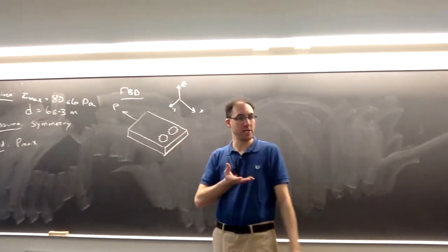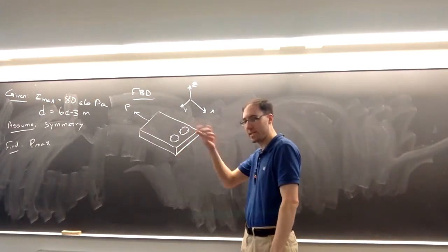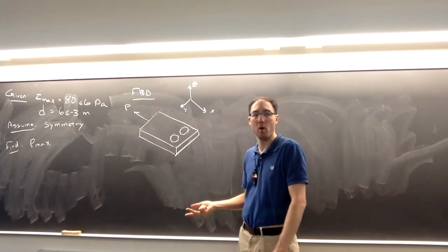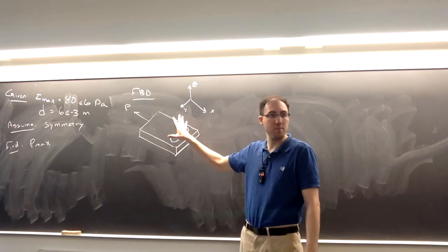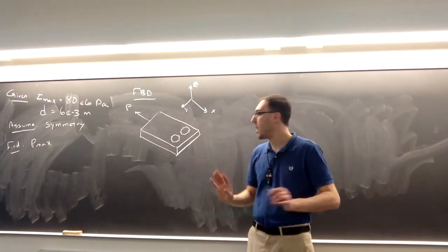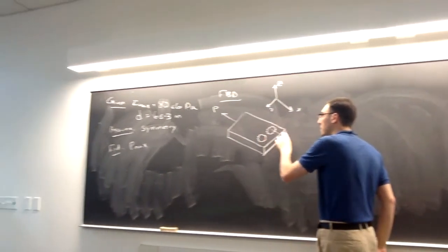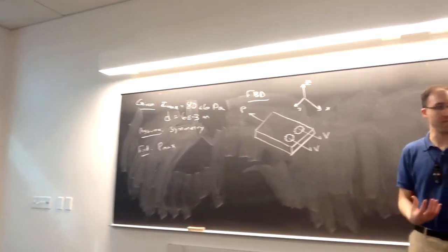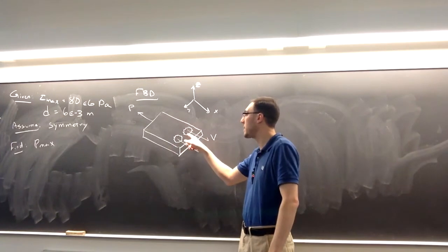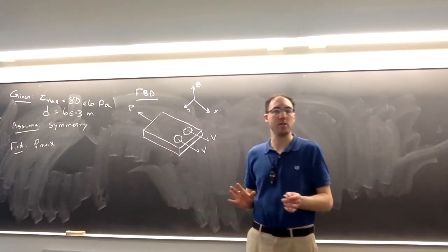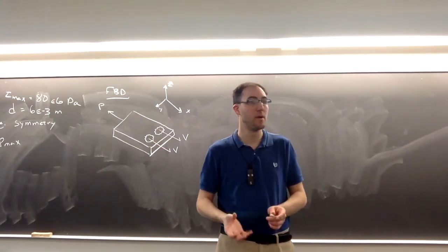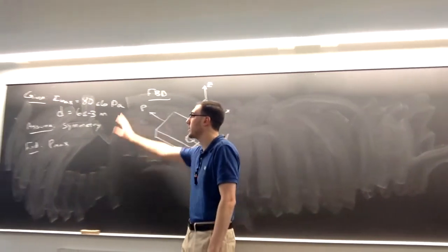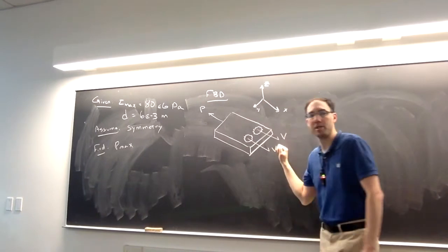Right. In general, just like we saw in the quiz, whenever you cut through a solid piece, you would be exposing internal normal force, shear force, and bending moment. For these problems, we're only looking at shear stress. I'm going to simplify it and just look at the internal shear forces. There could potentially be normal forces and bending moments there, but we're not analyzing normal stresses in this example, so I'm not going to draw those. Since we're only looking at shear stress, I'm only going to draw the shear force.